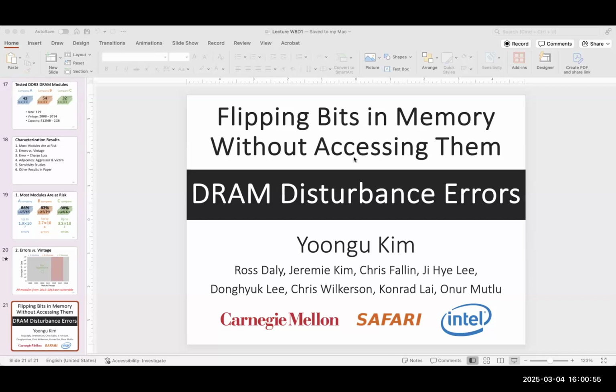So having a larger noise margin is a good thing. If you have a larger noise margin, your transistor, your memory is more reliable. But if I have a smaller noise margin, what will happen? As I showed earlier, even 0.01 volt of change can induce a bit flip.